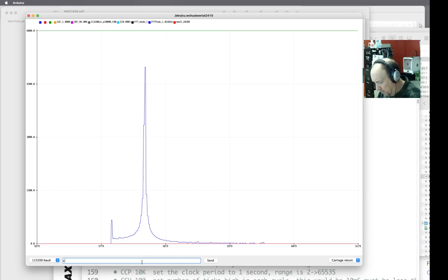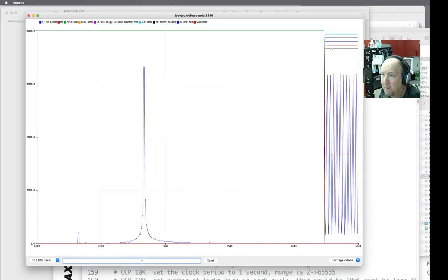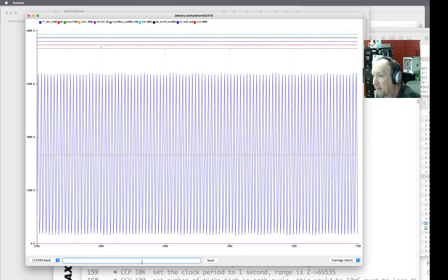Let's take that up. CSF 2K. There's a 2 kilohertz sinusoid, and it looks really good in the frequency domain. If I go back to F0, you can see that it'd be really nice if the scope sampled faster. But sorry, we're at the limit. We're at 10,000 samples per second, and there's nothing I can do to make it faster than that with an Arduino running at this speed. At least not that's going to fit in this amount of memory.